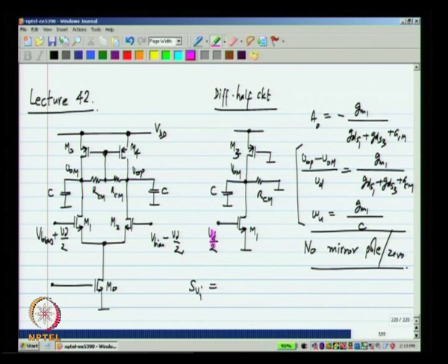You just have to calculate the input referred spectral density or the output voltage noise spectral density and then double it to get the corresponding quantity in the fully differential circuit. In this case we also have RCM which creates noise, but I have neglected the noise from RCM.